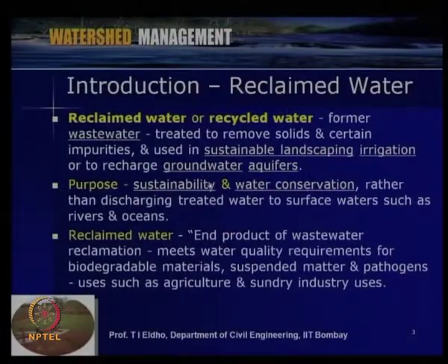So, we can mainly use the reclaimed water for non potable purposes, but sometimes if water scarcity is there, we can further use the reclaimed water for potable purposes also, through groundwater recharge and other ways. The main purpose of reclaimed water is sustainability and water conservation, rather than discharging the treated water to surface waters such as rivers and oceans.